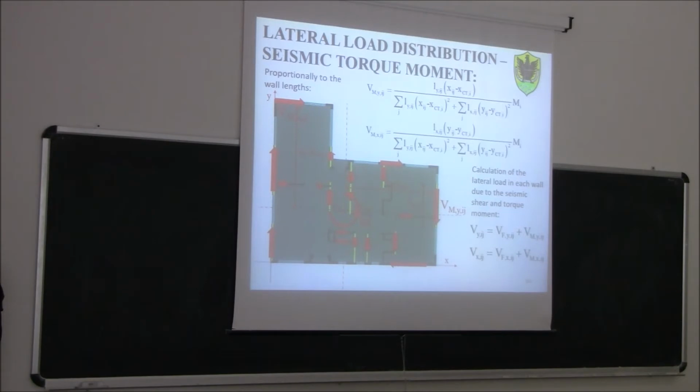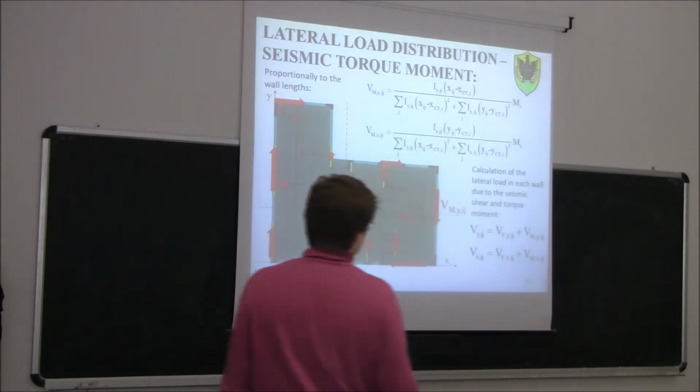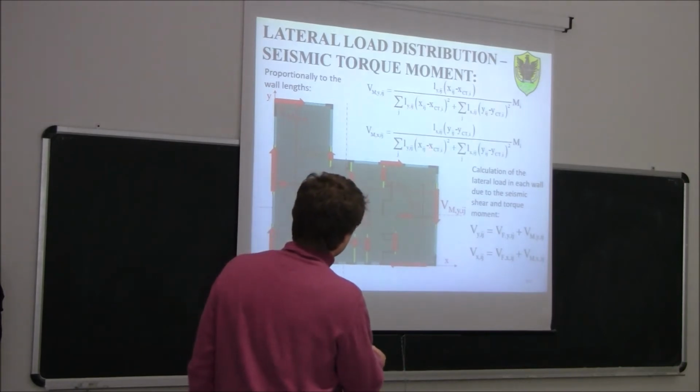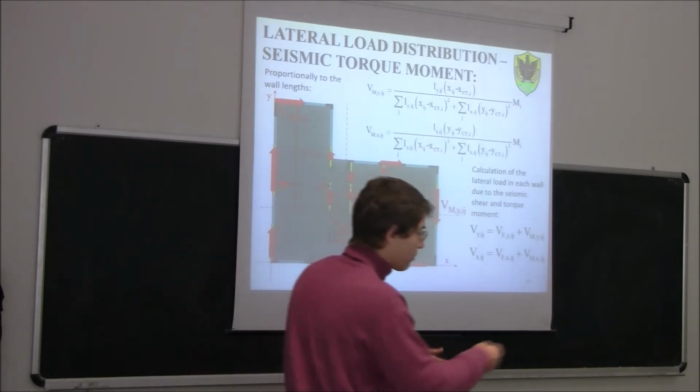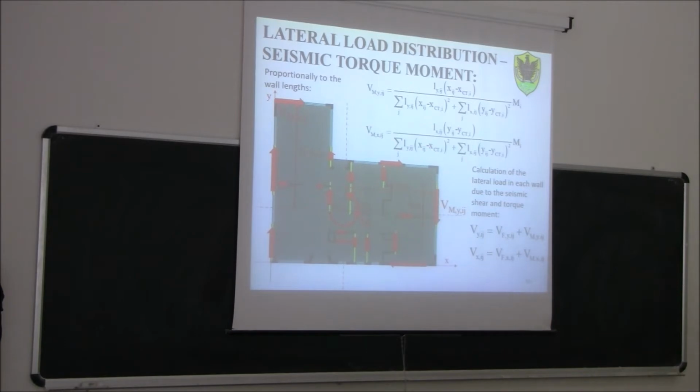Okay? This equation is formally the same or very similar to the one that we derived for calculating the shear force in a bolted connection subjected to a torque moment. In that case, we had the distance squared, while here we have an R, which was the inclined distance, while here we have this, let's say, parallel distance, parallel to the x and to the y axis. Okay?